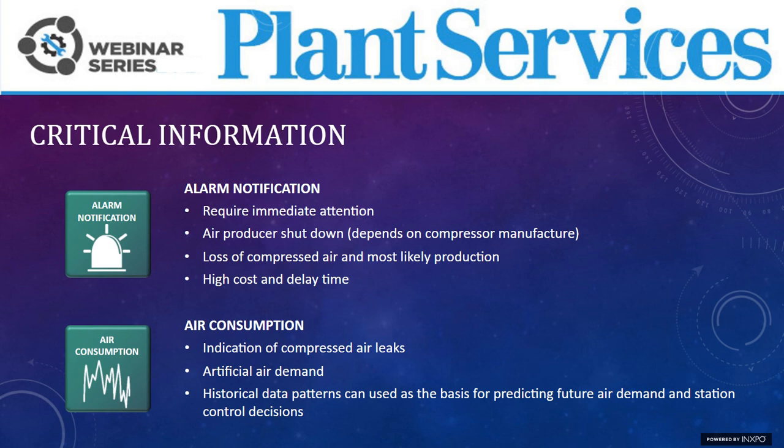Now here's another very critical piece of information. I highlight that in particular because alarm notifications, or alarms in general, will shut down a compressor or even prevent a compressor from running. Again, that highlights how important it is that alarms require immediate attention. It's good practice to set up an alarm notification pushed down to your mobile devices. Again, an alarm can lead to high cost and delay time.